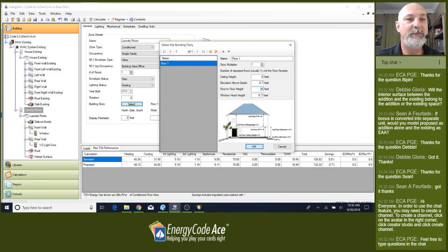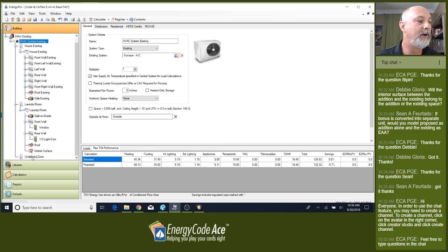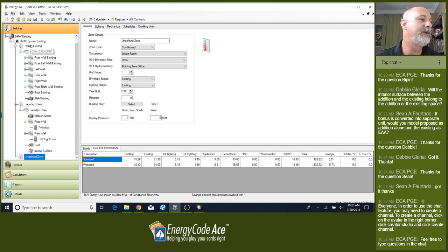Okay, let's create our garage zone, separate zone. As long as the garage zone isn't your first zone in your tree, you can put it anywhere you want. So I'm going to label this garage. I like to copy and paste text whenever I can. I avoid typing. We're going to say that zone type is a residential garage. Now, I have a practice of changing the bedrooms to 0. The software knows that if it's a garage, there's no bedrooms in there, but it's just habit. I get a little particular this way. It's not existing. It's brand new.